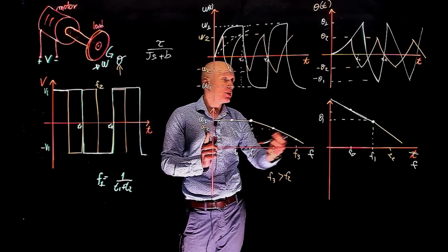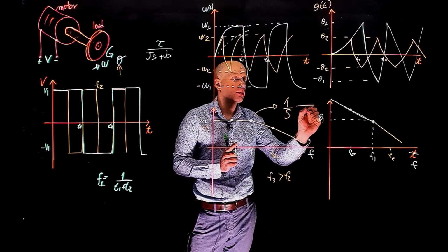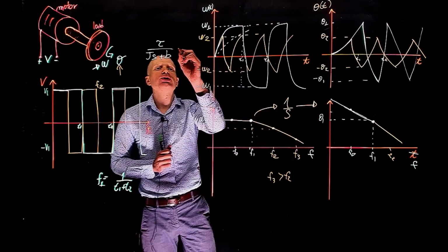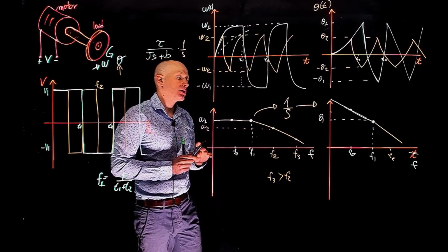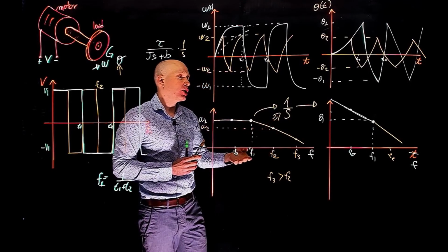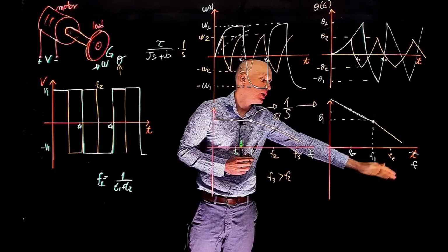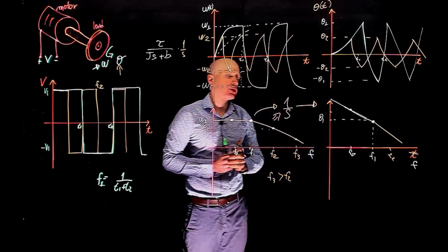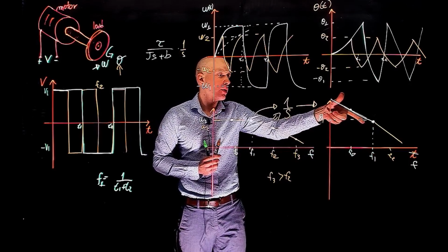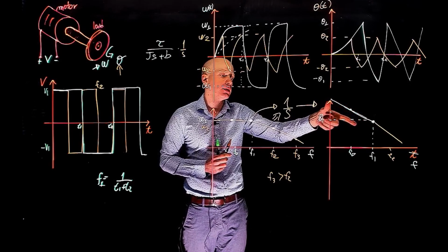speed. If you want to go from speed to position, what do we do? We have to integrate it. And by doing this integration, we are actually multiplying this function by 1 over s and adding a pole at the origin. This pole at the origin adds this slope that is now constant throughout the entire frequency spectrum. And that's why the slope that was 0 became non-zero here. We know that this is negative 20 decibels per decade.